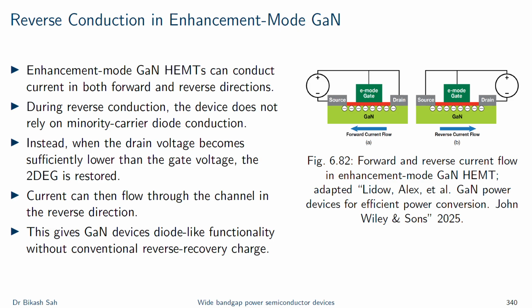A common mistake is that we assume GaN reverse conduction behaves exactly like a MOSFET body diode, but you have to remember that it does not. It is channel based and gate condition dependent.